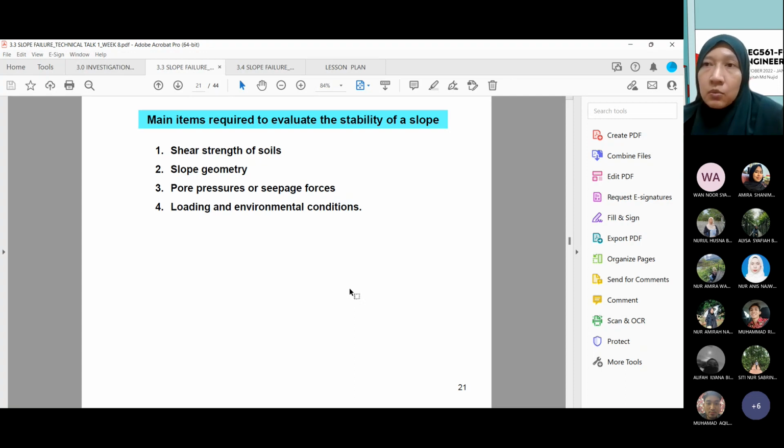Why? If the client asks why we cannot go more than that, you can say that through our analysis, this is what we found out. We have done some analysis on this kind of increasing loading. We can see the output can cause slope failure where FOS is less than 1. That's how you justify your design when you need to produce a report.